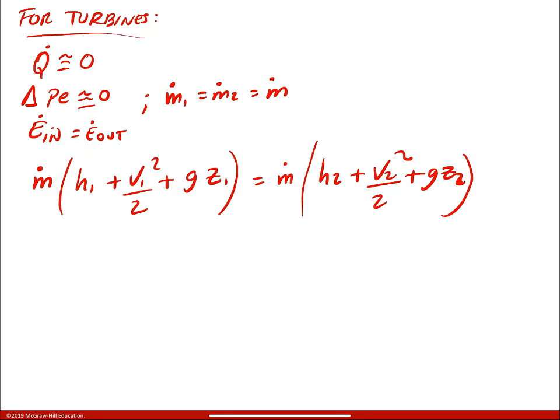What else? That would be the question, right? The answer is that the turbine will produce work. If the turbine is producing work, that means the work is coming out of your system. So now I need to add the work rate that is coming out, the power coming out, so everything will be in kilowatts. This whole thing will be kilowatts, kilowatts, kilowatts. Perfect. We can work with this equation.